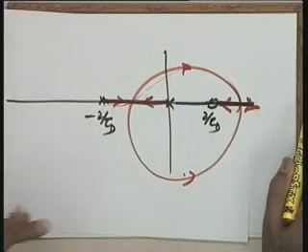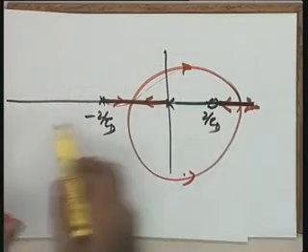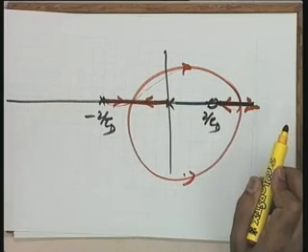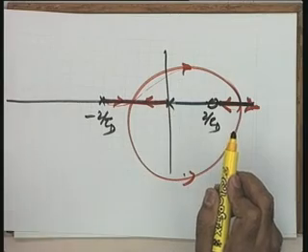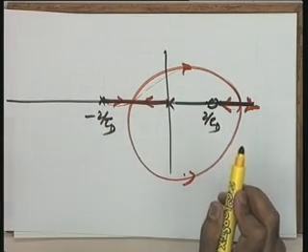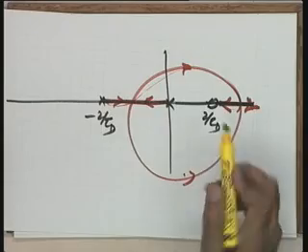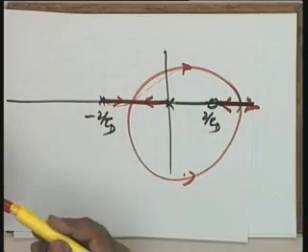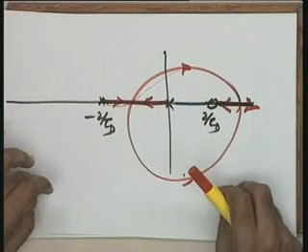I again repeat, the only change is this in terms of real axis segment search and replacing 2q plus 1 by 2q whenever there is a minus sign associated with it, and an example of this is that of a dead time, which always gives you this particular form when you approximate it by a rational function.